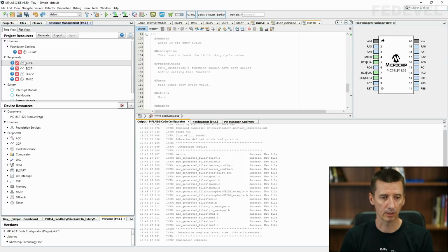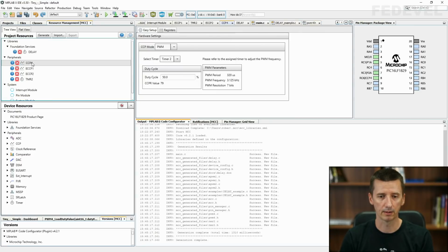If we go into the CCP4, when I open it, then this is the value what we would like to put there. For 100%, if I put here 100, enter, we would like to maybe use 159 value for the function. And from my experience, I know we actually need to use 160, okay? Then the duty cycle will be 100%, because this is just approximate number. It's hard to calculate the exact numbers.